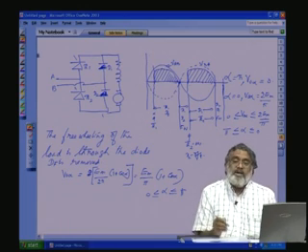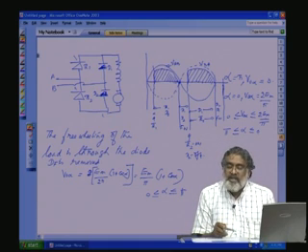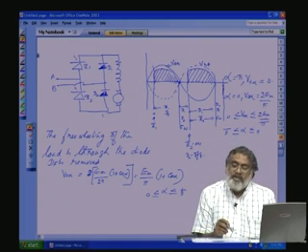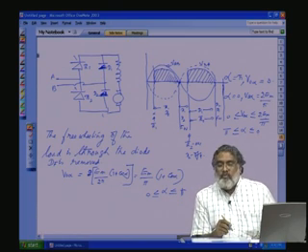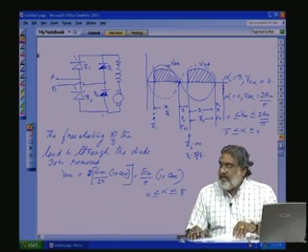So, many speed control systems for DC motors use AC to DC phase controlled converters with firing angle control. These types of converters, even though 4 switches are there, only 2 are controllable. We can only have positive voltages. That means only one quadrant operation is possible. What is meant by one quadrant? Let us see.